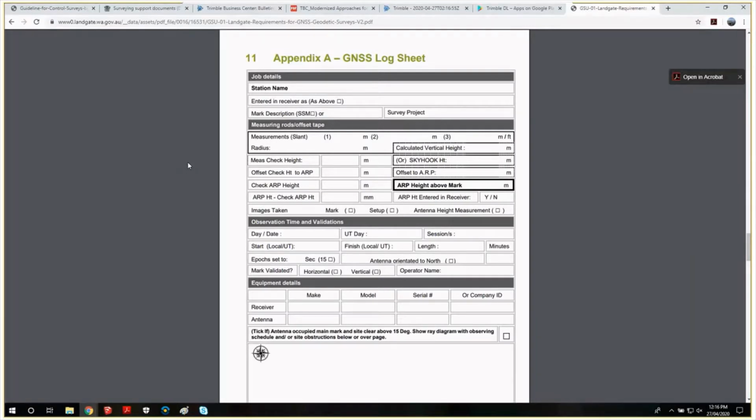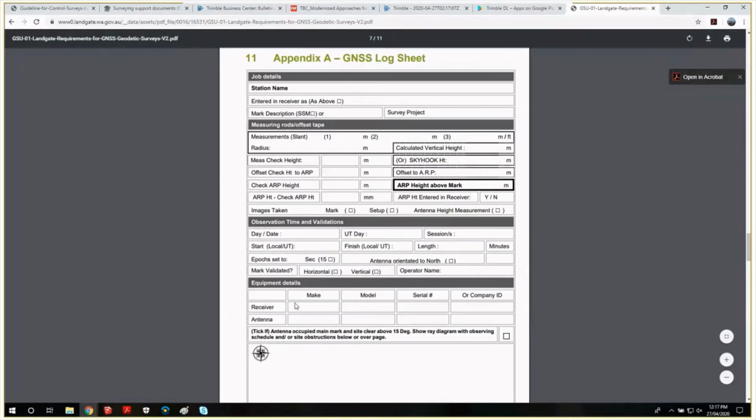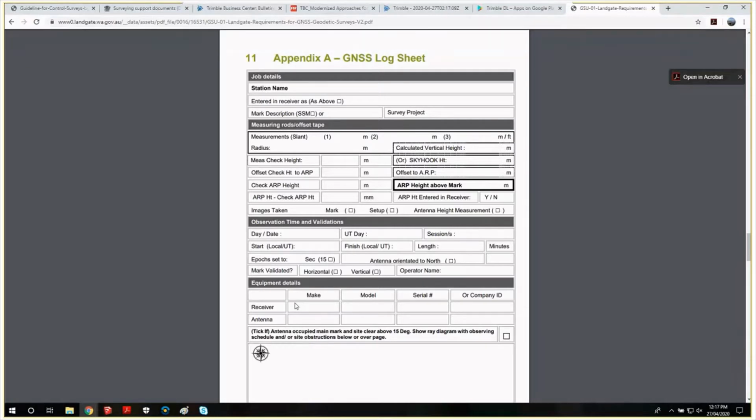When we get to TBC and we are entering the data, there is a screen called the Receiver Raw Data Check-in, and this allows us to go through the data and just make sure that it's fine. And if we've got really well booked GNSS log sheets, then we can pick up any blunders or mistakes, hopefully, and correlate that to what was done in the field.